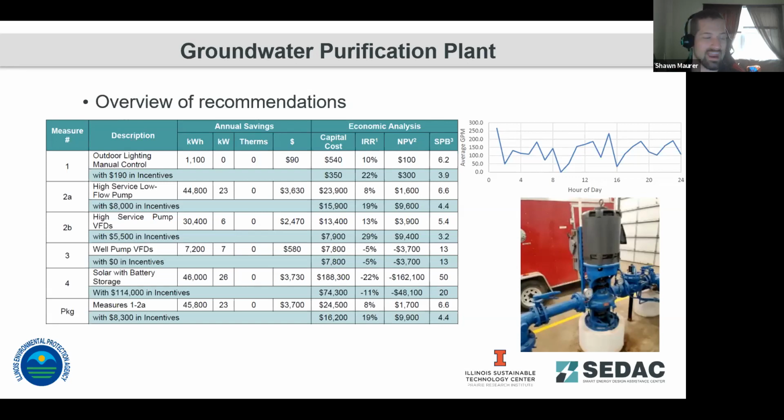And when you're looking at average consumption for a community, you expect it to shift a little bit day to day and smooth out on an average profile. But when you have a consistent spike over and over again, that's a good indication that there's leakage in the system, and then your system is kicking on to replace that leakage, and it's at a fairly constant rate.